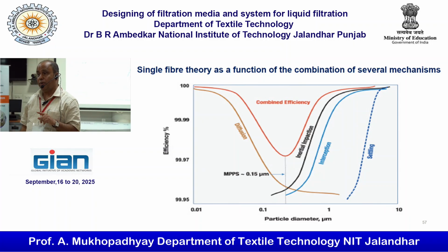That is why, for MERV, try to find out how MERV is measured and what the classification procedure for MERV is. The point I am trying to say is that if you can ensure the capture efficiency of the smallest particle, then smaller or larger than that, we will always get higher efficiency. That is the logic why we go for 0.3 micron testing.